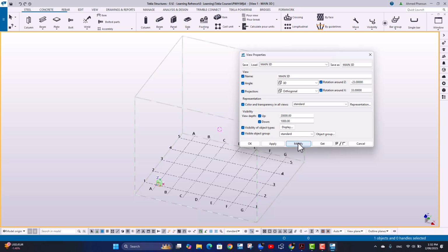So the second concept, let's refresh now. The first concept is that if you need to modify anything, just double click on it. The second concept is that you can make use of saved settings or saved attributes for everything in Tekla, including beams, columns, red lines, plates, whatever object in Tekla, you can use the save and load attribute with the properties you are caring about. Is it clear? Good. Let's now transfer to another place, which is the view properties itself.